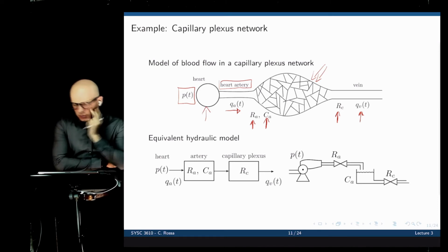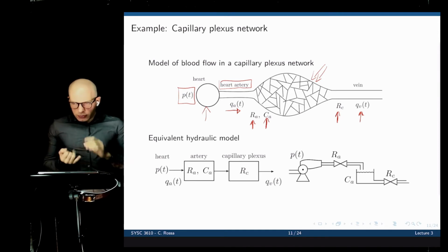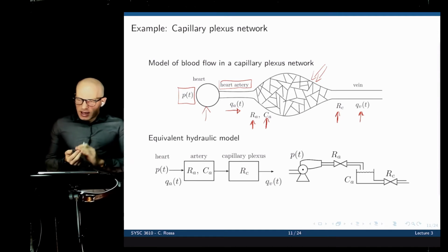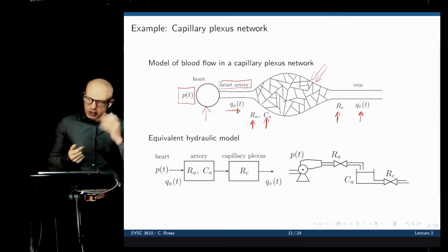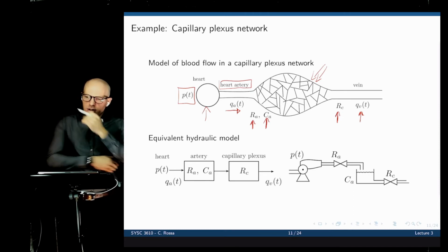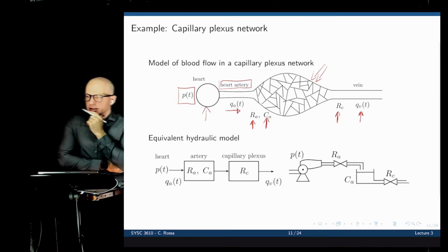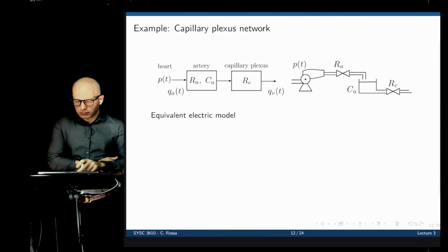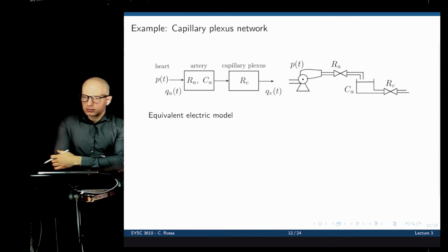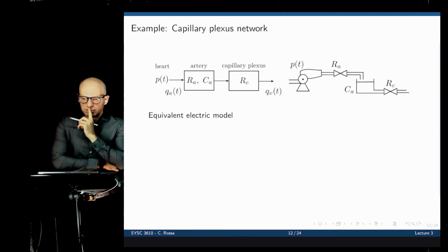So what do we see? Key points here are some way to store energy, some resistance to flow, the input pressure, and two different fluid flows, one before the reservoir and one after. What would be an equivalent electric system that would have the ability to display the same thing? You could just put a voltage source, a resistor, a capacitor, and then another resistor all in series. But you could simplify it and just put one resistor with the summed resistance.